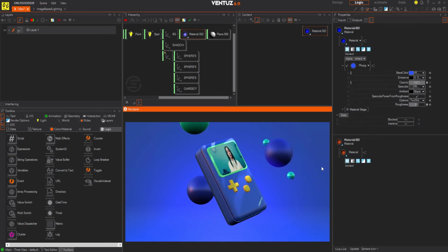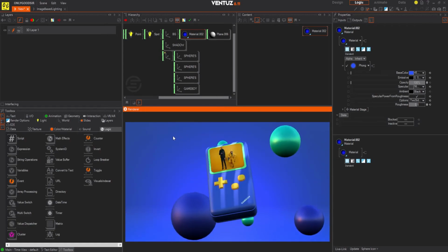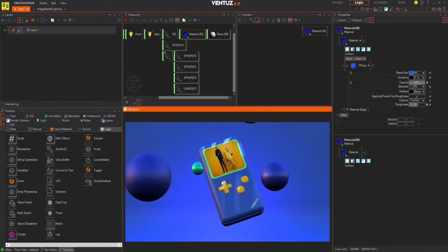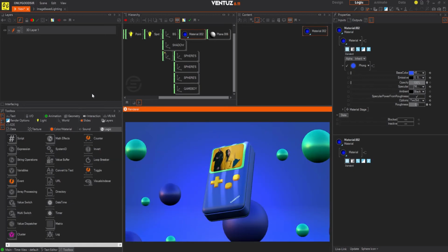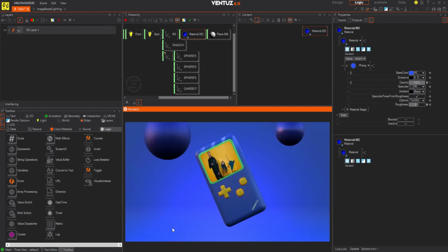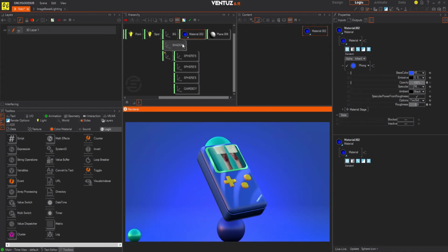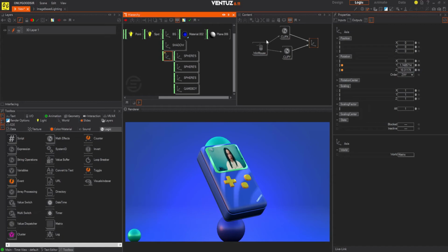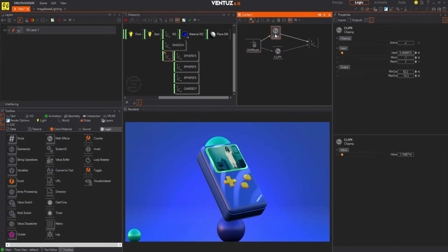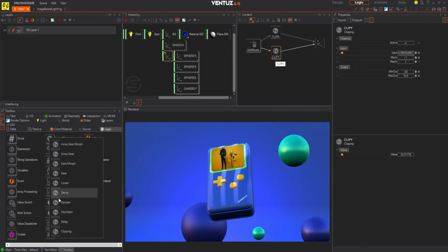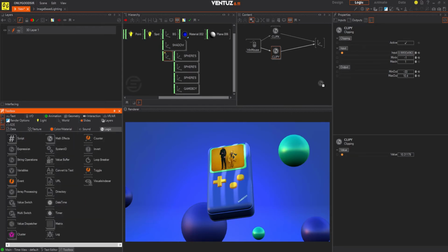Now let's add some depth of field in this scene. And you may notice that when the mouse leaves the screen, it's very snappy. So I'll also just move this across the screen, and it looks very snappy as I drag along. So what I can do is smoothen this out before we do the depth of field stuff. So let's smoothen this out by adding some damping using an oscillator perhaps, or you can use an ease. I mean, you have ease dampers, linear, ease morph. You've got loads of options. I'm going to use the oscillator.